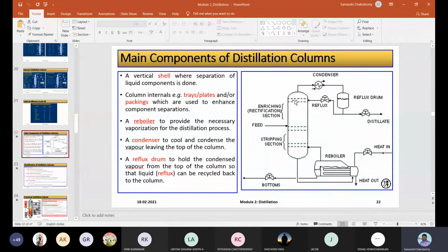So vapors are going to carry forward the liquids present in the top part of your distillation column directly to the condenser. You don't want the condenser to deal with your liquid. You want the condenser to deal with your vapor. So puking will only happen if the vapor flow is exceedingly high. All the liquid present in your tray, because of this high vapor flow, is going to be carried over, and through this line it will come to the condenser, and then it will obviously get stored in this reflux drum. So your product quality, your operation, everything is going to be detrimentally affected.